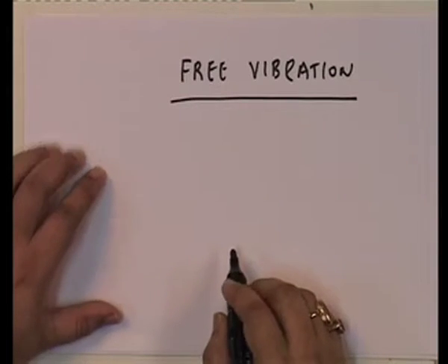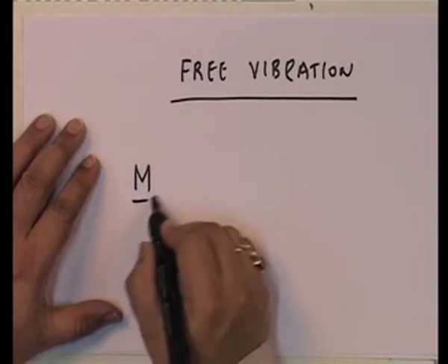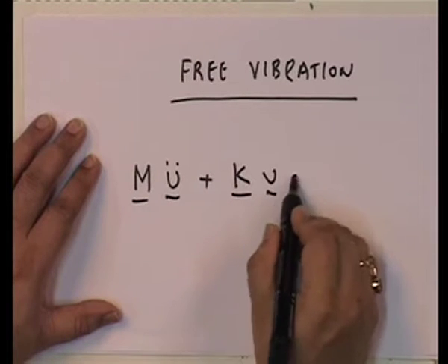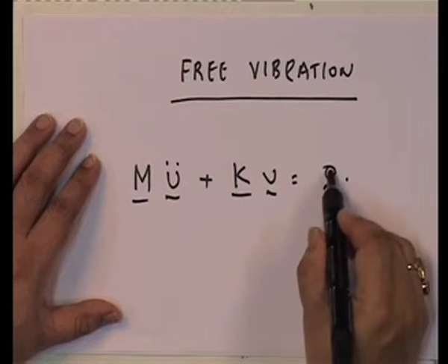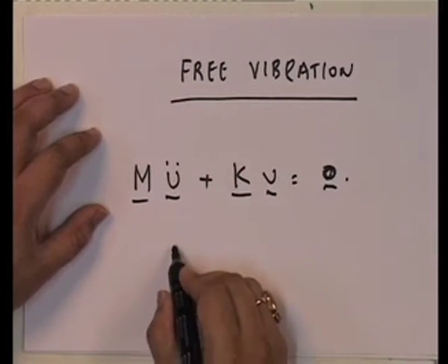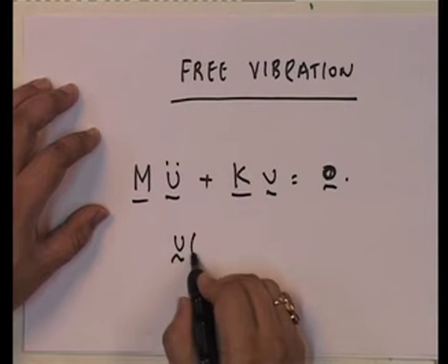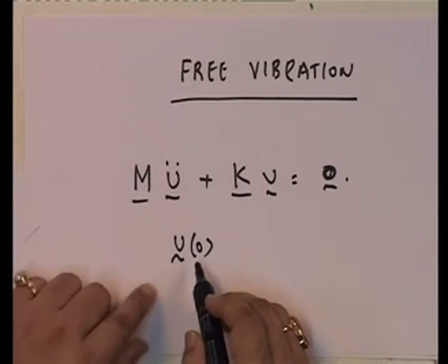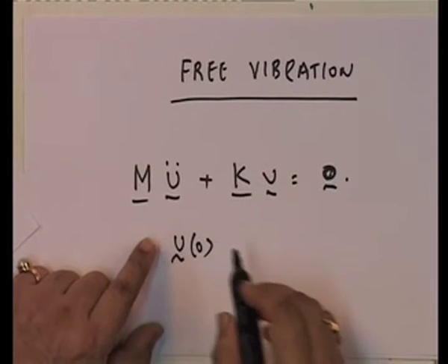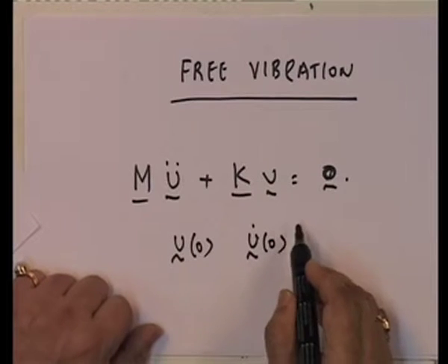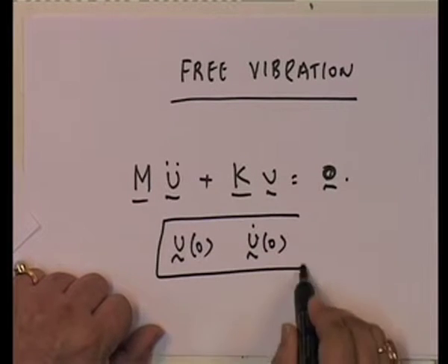And in free vibration, the equations are as such because there is no load. Free vibration means it is freely allowed to vibrate, where you are given initial conditions. Now, this is the issue, that this is a vector. So, you have to be given all displacements at time t equal to 0 and corresponding velocities.